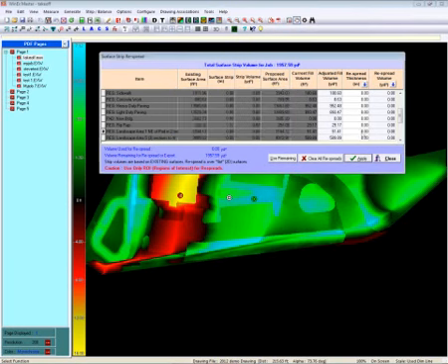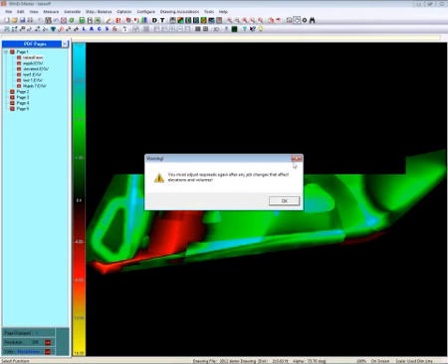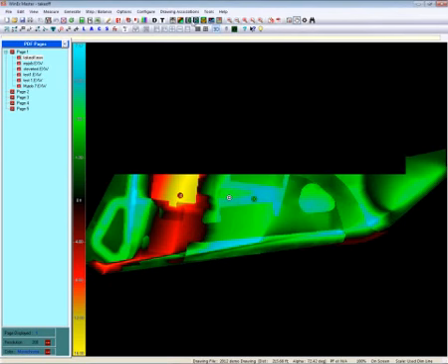We've talked it over. I can, actually that was landscape area 1. And let's say he said I can spread 13 inches along that whole site, and I'll hit apply. And that 13 inches is equal to 40.77 cubic yards. So you can see my respread has gone up, but my dirt for export has gone down. You can continue to do that so you can almost balance the site. We also have the ability to go in and balance the entire site. And by the way, after you move dirt around, you've got to reprocess the job, obviously. So we go back in and we reprocess it.